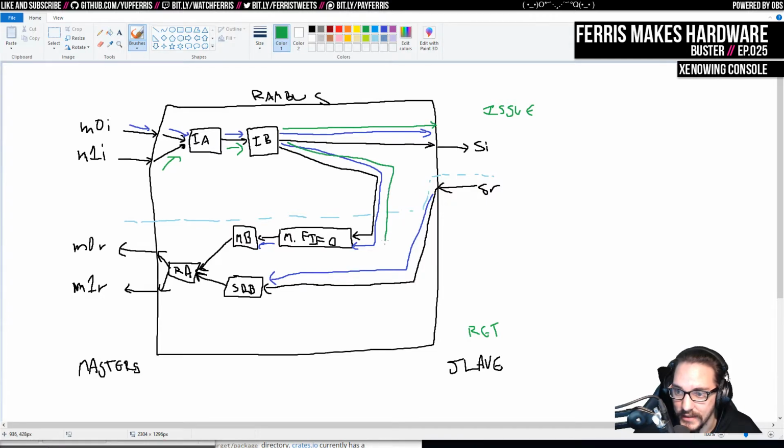And again, this goes in here. Then on the following cycle, we have something in this buffer, we have something in this buffer. Great. We're going to merge that here and send this on its way. We're looking good. In that same cycle, the green data comes here and this green data can come back. Then on the following cycle, the green data gets merged in this arbiter and goes on its merry way. Great. That's what we want. And as long as we have write through on this FIFO, it should be possible to implement this.